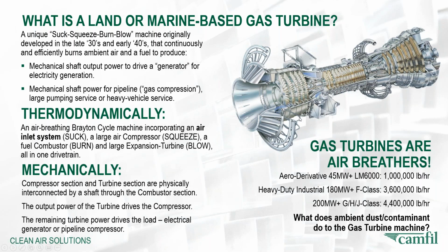Thermodynamically, a gas turbine is an air-breathing Brayton cycle machine incorporating an air inlet system, or the suck section, a large air compressor, which is the squeeze section, a fuel combustor, or the burn section, and a large expansion turbine, the blow section, all in one drivetrain.